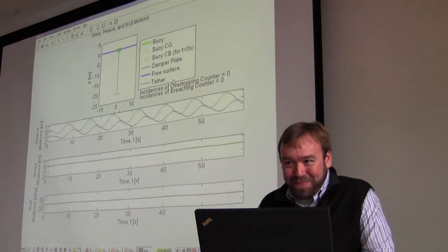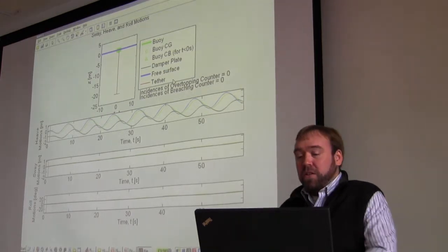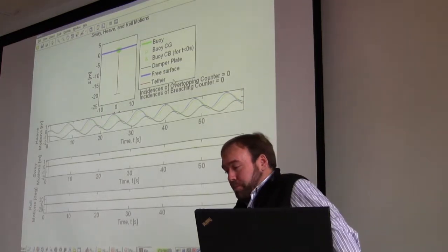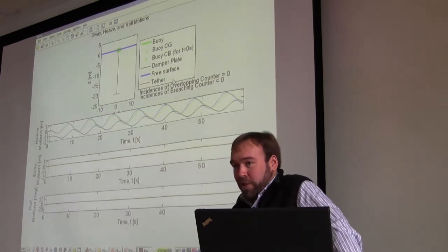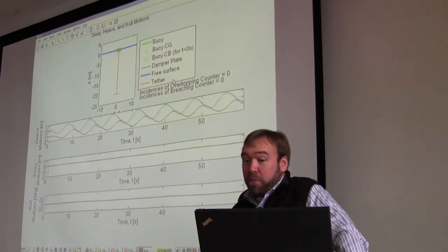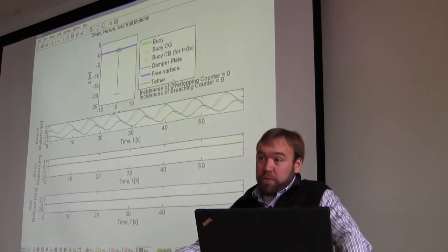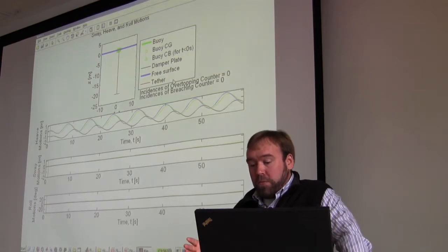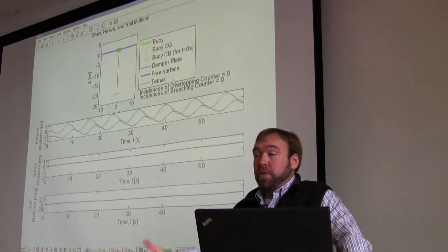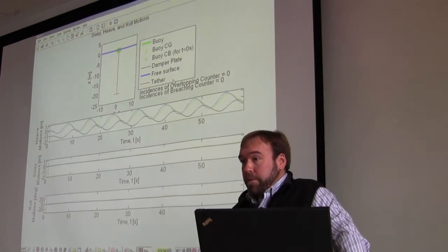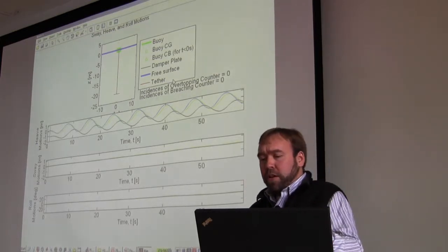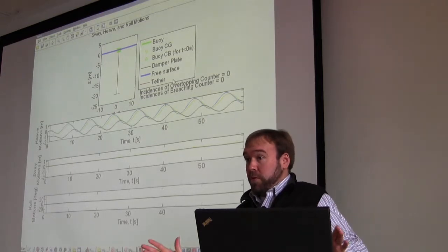How do you define your geometry in this? Can you do it in Aqua? Exactly. The geometry that is important is defined in either WAMIT or Aqua. Okay. Because then that gives you the impulse response function. Actually, what's being read in here is the frequency domain response, the RAOs, from either WAMIT or Aqua, not necessarily the IRFs. And the geometry that I'm using here basically is just for the visualization.